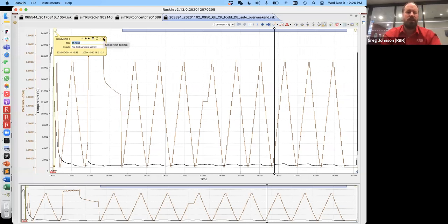These are persisted in the underlying data file so that you can then look at those annotations in any downstream processing tool as well. The instrument, if it is set up for profiling at faster than 1 Hertz, will also automatically detect downcast and upcasts and separate them, group them into profiles, but keep them separate as downcasts and upcasts. And you'll hear me talk about that a little bit when we're looking at RSKtools in a few minutes. The variety of annotations that are in here can be selected, and then you can navigate by them. You can add other